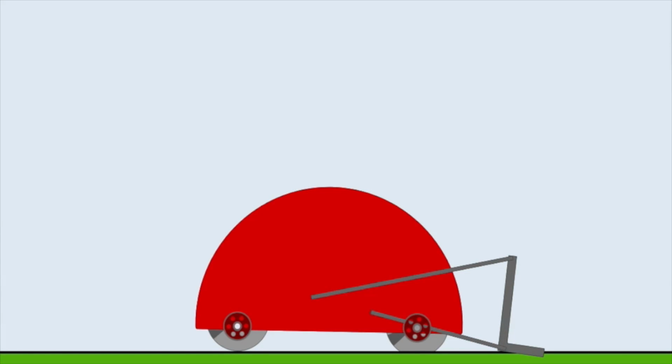So imagine we have this robot that has to pick up balls or other objects and drop them into a hopper. We need to attach a linkage to the front of the robot to accomplish this. The problem is, how do we know how long to make the links or where to attach them? This is a problem that can be solved through graphical position synthesis.